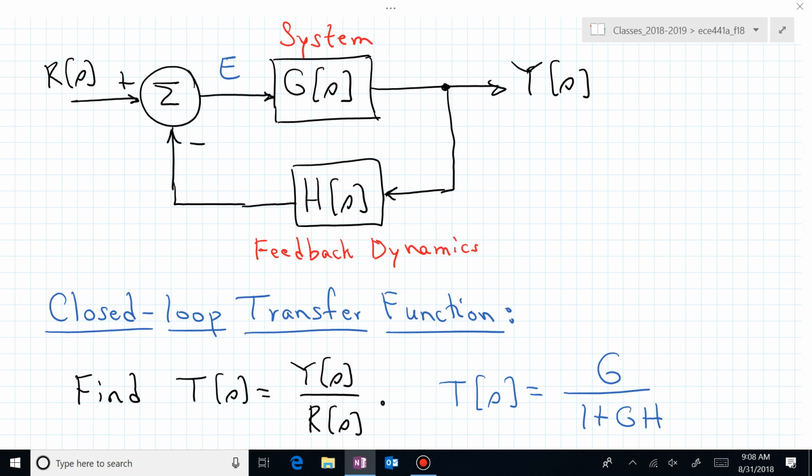That usually is a good way to start eliminating this result that sometimes happens as you feel like you're chasing your tail. You just keep circling and writing equations and you're not getting anywhere. But essentially what you want is one equation that contains only the reference signal R and the output signal Y, and you want to now solve for the ratio of Y over R.